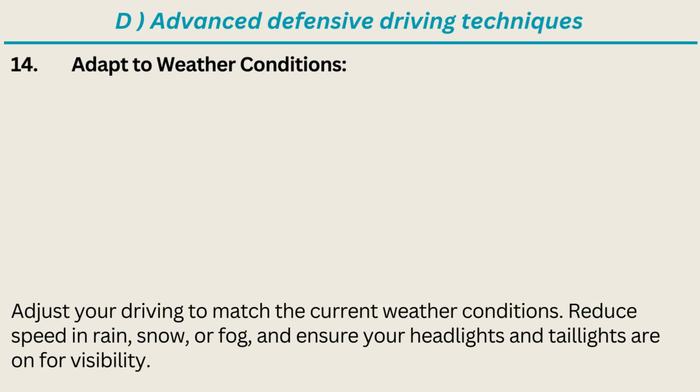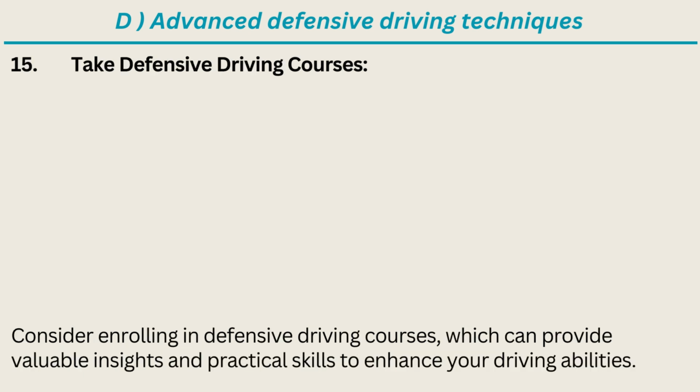14. Adapt to weather conditions. Adjust your driving to match the current weather conditions. Reduce speed in rain, snow, or fog, and ensure your headlights and taillights are on for visibility.